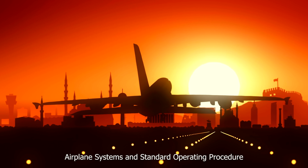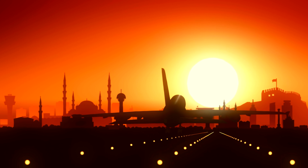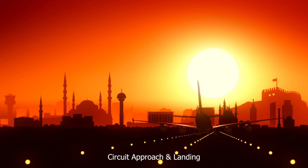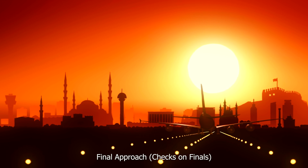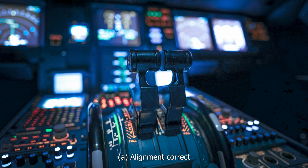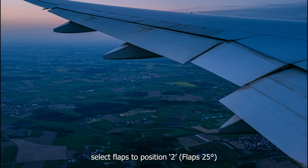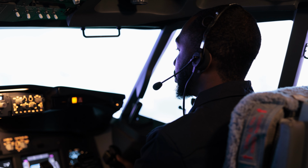Airplane Systems and Standard Operating Procedure. Chapter 5. Circuit Approach and Landing. Final Approach, checks on finals. A. Alignment correct. B. Throttle to idle. C. Perspective correct. D. Speed below 55 knots, select flaps to position 2, flaps 25 degrees. E. RT call. Maintain speed 50 knots.